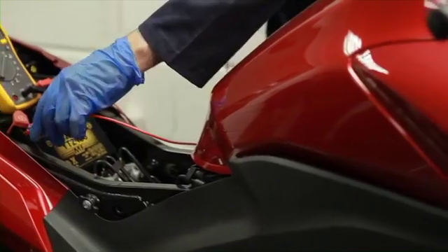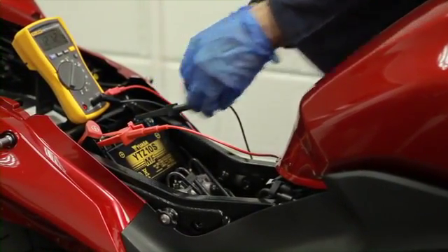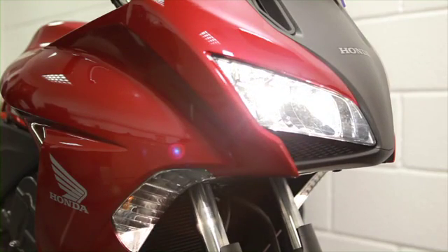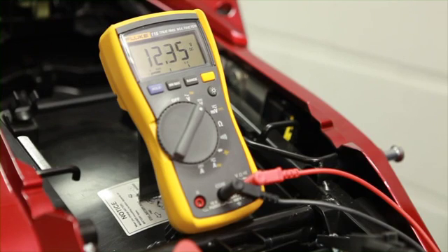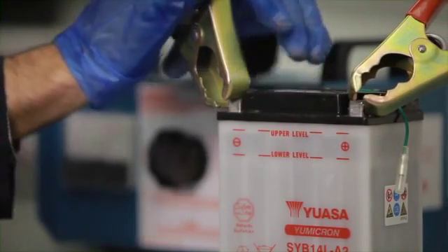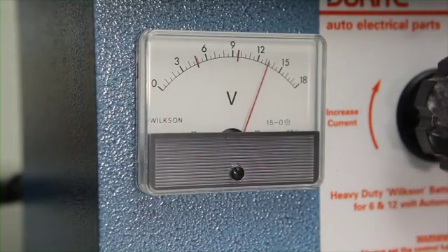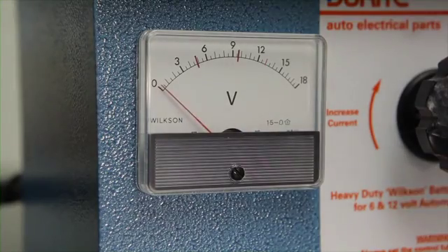To perform a loaded test on either type of battery, connect the voltmeter to the vehicle's battery with the engine off. Turn on all the lights and check the reading on the meter. A 12-volt battery should have at least 11.5 volts with the lights on. If the voltage is below this level, recharge the battery. Alternatively, there's a high-rate discharge test. This test uses a special device to apply a load of 3 times the battery's ampere-hour rating. After applying the load, measure the battery's voltage. A conventional 12-volt battery should have 12.4 volts, and a sealed-type battery should have 12.6 volts.